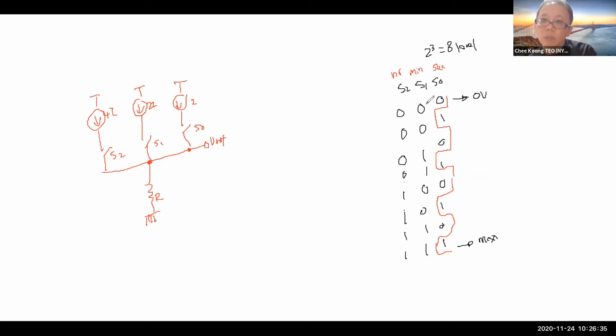The subsequent bit, after the first one goes by one cycle, changes state, and after one more cycle, changes state again. This one also waits for the lower significant bit to go one cycle, then it changes state.